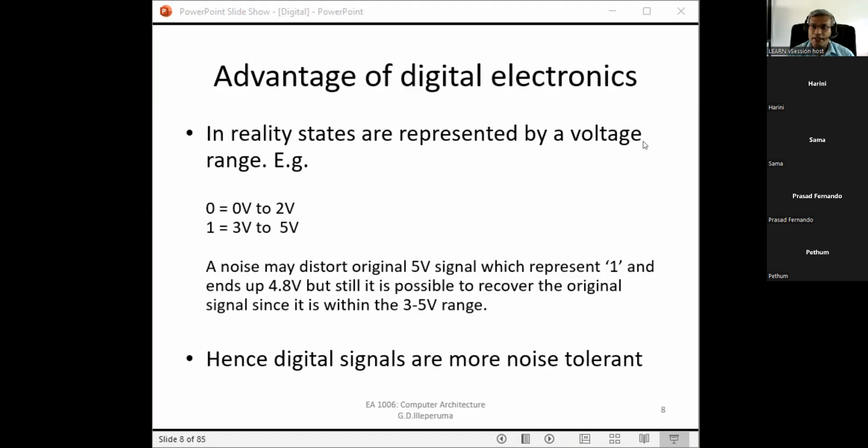So when you're building a circuit, check whether you are using the same type of ICs. If you try to use a 3.3 volt microcontroller with a 5 volt different logic IC, it will not work. Right? So that's one thing.